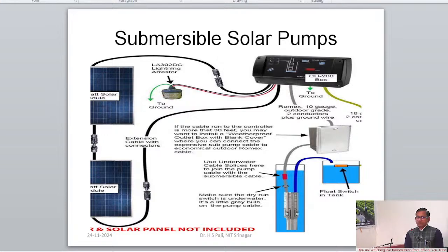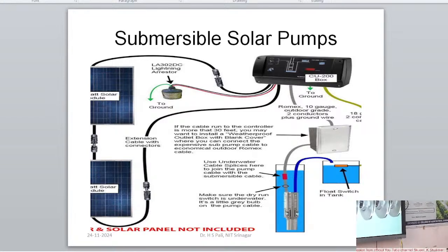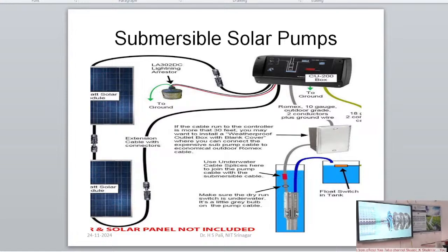You can see how the impellers are throwing the water outwards. The impeller blades are the backwards curve type. Similar to the centrifugal pump, backward type blades are used here. Many impellers are connected onto a single shaft, and this shaft is driven by an induction motor. The water enters through the eyes of the impellers, and they are then thrown out radially due to centrifugal action. This way, the water particles gain both kinetic and pressure energy.